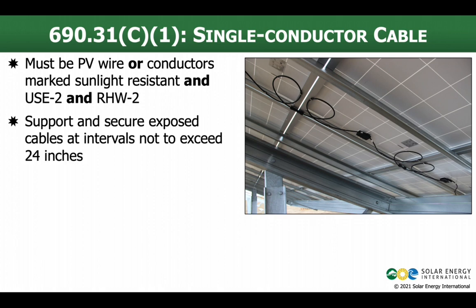Now, when it comes to managing these wires, we have to support and secure them every 24 inches. So this is clear guidance on wire management. We'll talk more detail about wire management in a little bit. It's something that we've got to do on our PV arrays, and when I look at the image on the slide here, I like what I see. Sorta. There's one thing I don't particularly love, however. Maybe you see it already. We'll get there in a second.